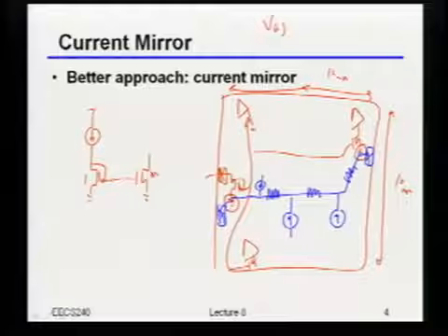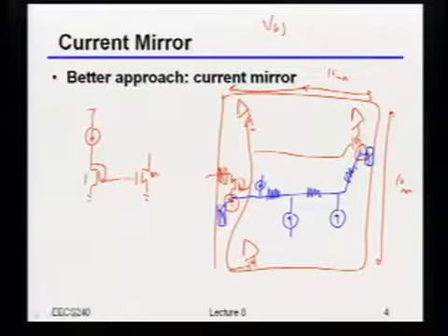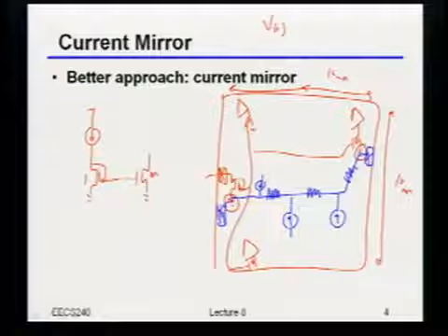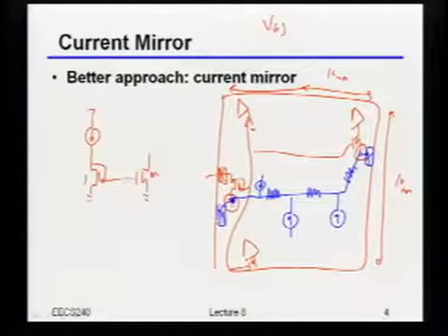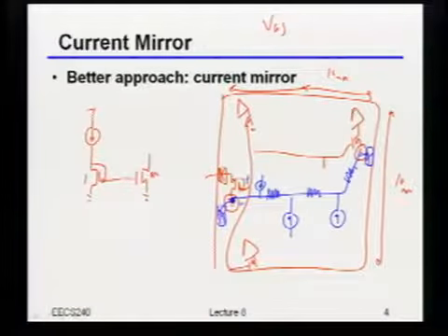All the rest of my active circuits are going to have current flowing through the ground wire. So whatever I called ground, which sets the VGS on my diode-connected device, even though I take that wire and run it over to the other side of the chip for what I usually think of as the bias voltage, unfortunately the other wire, which is ground, is not actually at the same potential here as it is over there.